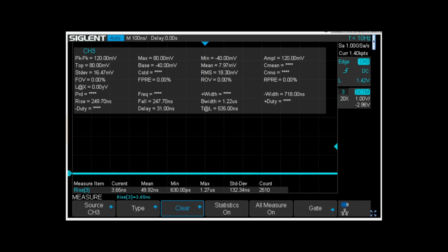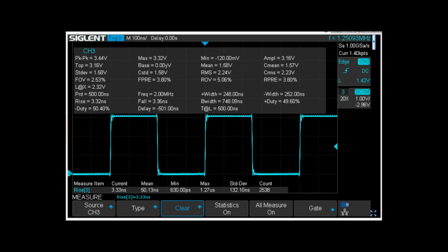And so now I'll hold the connector on here, and we see that the waveforms look pretty good. But notice that the amplitude is going up and down. The higher amplitude is the 16 milliamp drive strength, and the lower is the 4 milliamp. So the probe is loading the circuit sufficiently that with a drive strength of 4 milliamps, the Raspberry Pi isn't quite able to provide enough current for this probe to maintain full amplitude, and that's not a good thing.